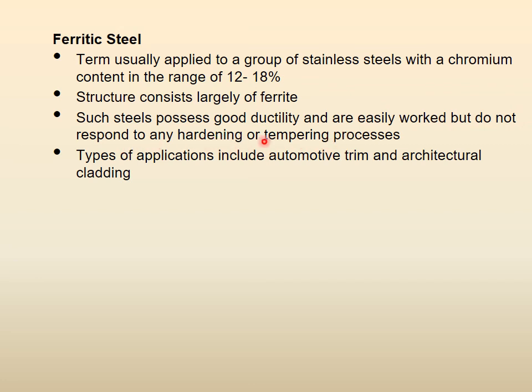This is huge. When I was studying steels at a higher level, in masters and PhD, this became very big. I thought that all steels can be heat treated very easily, but I came to find that many of the ferritic steels, which are stainless steels, cannot be easily heat treated. So this was a major piece of news for me. Types of applications include automotive trim and architectural cladding and a lot of other places where stainless steels are good. So this is what ferritic steel is.